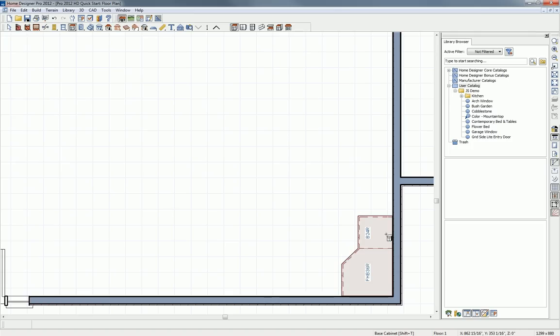I'll make my way around the kitchen and create a basic L-shaped design. To make a change to the dimension, I'll place a cabinet and click on it again, and take the Editing Tools bar and drag it out.